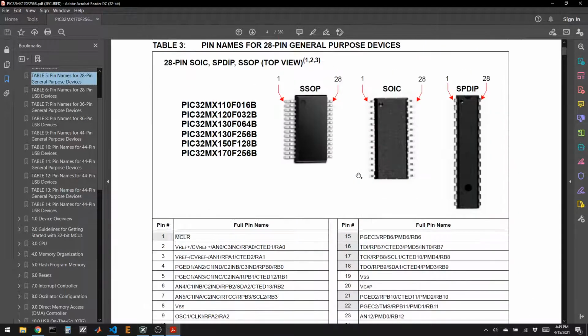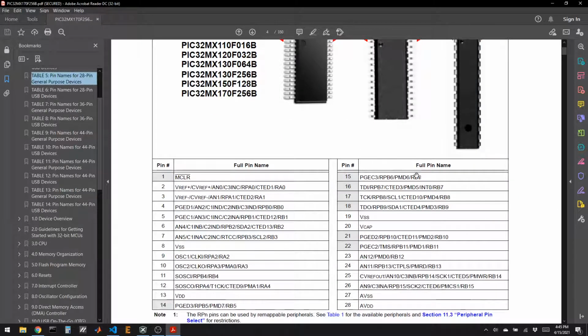The 200 series, of course. Okay, there, the 100 series. B6 is pin 15, so the bottom right pin, and B7 is one above it. So I'm going to find the TX pin on the USB friend and connect it to the RX pin on the PIC, which is B6, pin 15, and we'll do the opposite for the other pin.